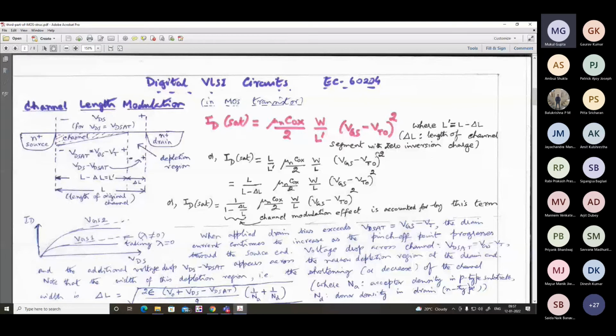And similarly, that was for an n-type polysilicon gate. Suppose you have a p-type polysilicon gate, and we say that the acceptor concentration is 10 to the power 20. Then, for simplicity, we'll assume that the Fermi level is almost coincident with EV. So for a degenerate p-type semiconductor, the Fermi level is coincident with EV, the top of the valence band. Whereas for a degenerate n-type semiconductor, the bottom of the conduction band will be almost coincident with EF. So EC and EF will be coincident for degenerate n-type, whereas for degenerate p-type, EV and EF will be taken to be coincident.